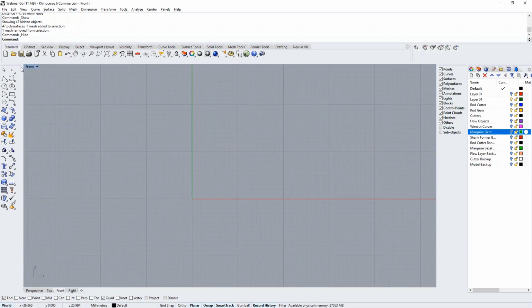So 9.5, we're going to create a marquee shape by using an arc. On grid snap, I'll start here, boom, and use relative positioning, relative, negative 9.5.